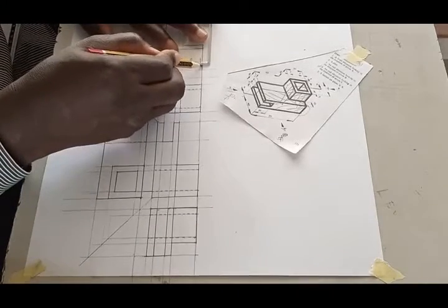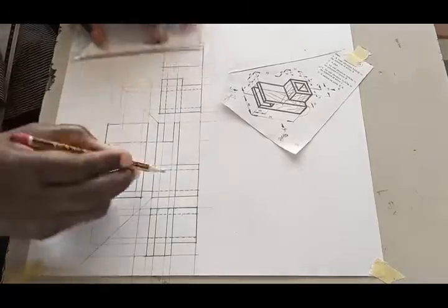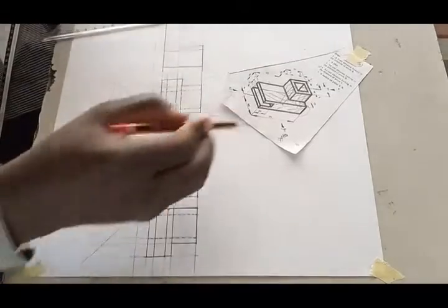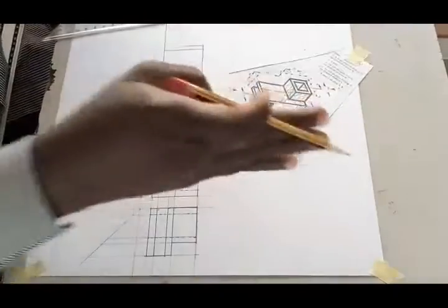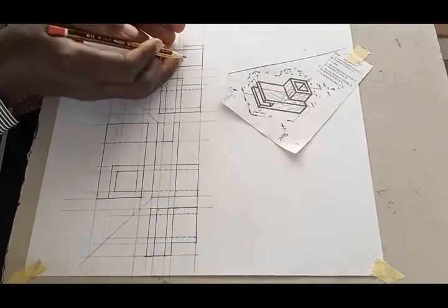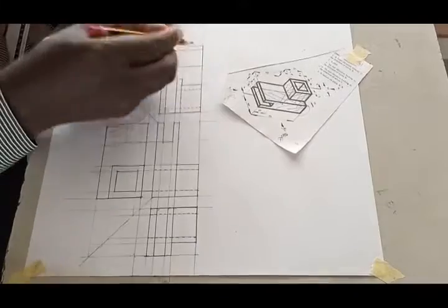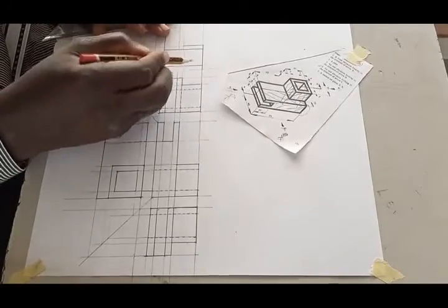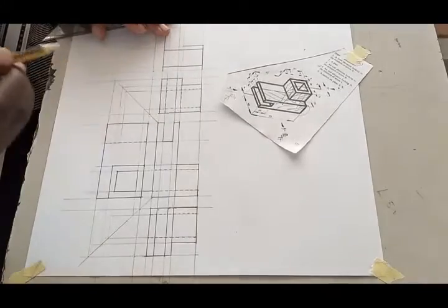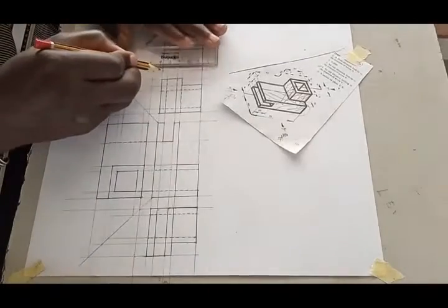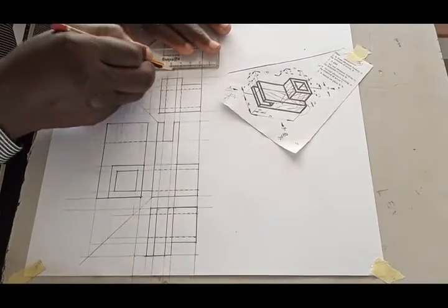Remember, on the other one, on this one, it was hidden line, because we are viewing from here. We had not cut it open, but this time around we have cut it open, so we can see the hole. So this place is no more hidden from us. So this line is not hidden. This edge and this edge, they are no more hidden. We can see them. So that's why they have been drawn in thick lines.